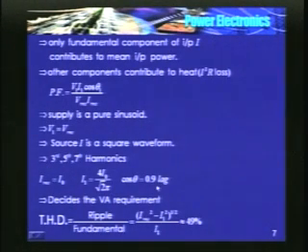It is lagging. Remember, in almost all power electronic circuits, power factor is lagging. So, this factor decides the volt ampere requirement. The size of the equipment that is required to feed a load depends on VA requirement and not just on power. What is the total harmonic distortion?